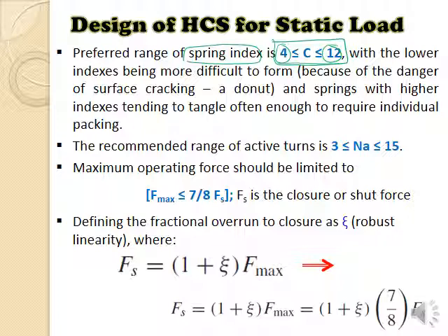The second is a recommended range of active turns, meaning the number of active coils. The number of active coils should be between 3 and 50. Then we will see what the maximum operating force should be.